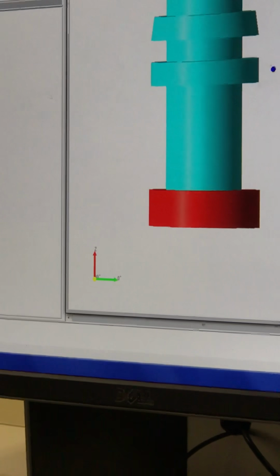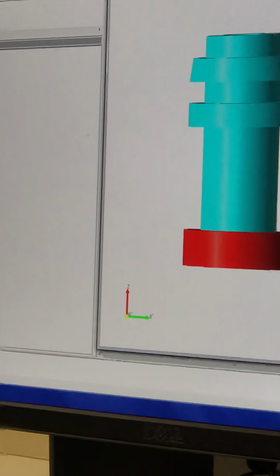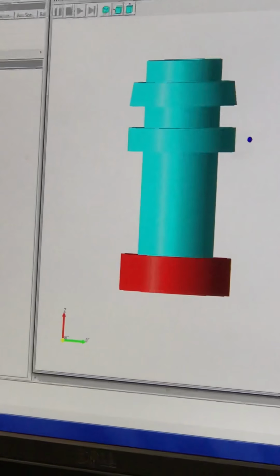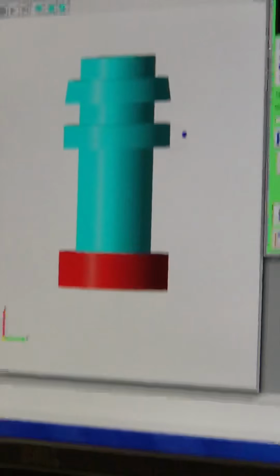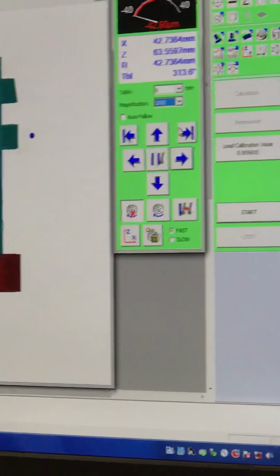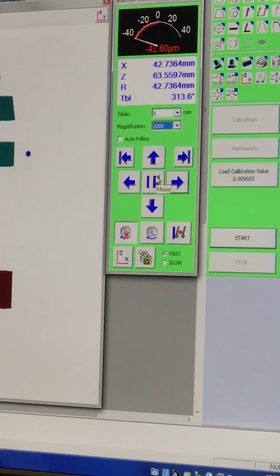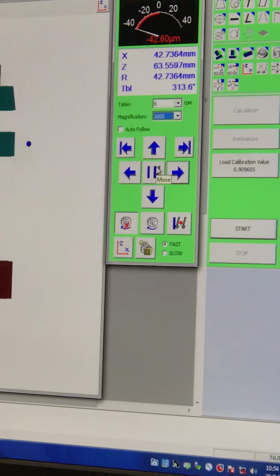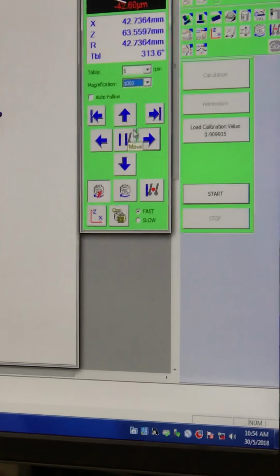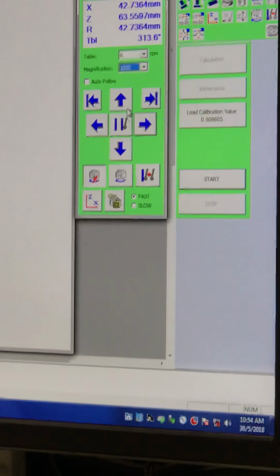Then you can start. Alright, concentricity, start. Must change the magnification to 1000. Change to 1000. Anything else? Click on the concentricity. I'll click already. Then auto set. And where? Start. Measure where? First, measure. Let me see. Measure on top one.